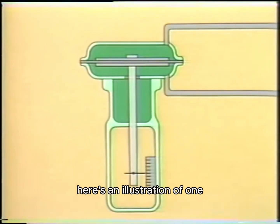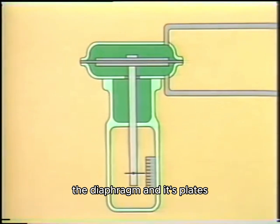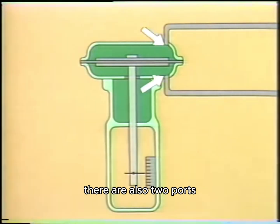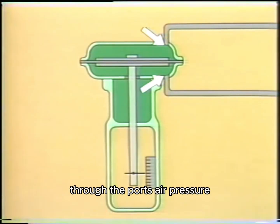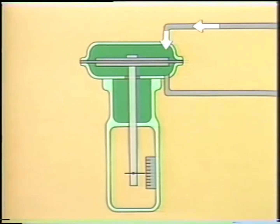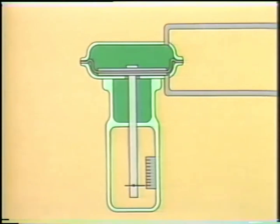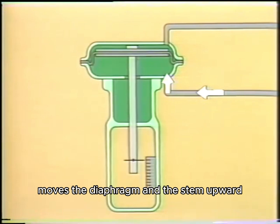Here's an illustration of one. One big difference is obvious. There's no spring. Instead, the diaphragm and its plates divide the casing into two equal chambers. There are also two ports, one on each side of the diaphragm. Through the ports, air pressure can be applied to either side of the diaphragm. In this illustration, pressure applied here moves the diaphragm and the stem downward. Pressure applied here moves the diaphragm and the stem upward.